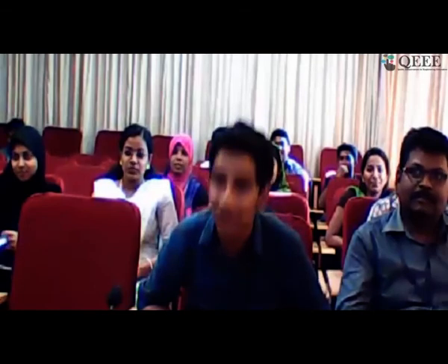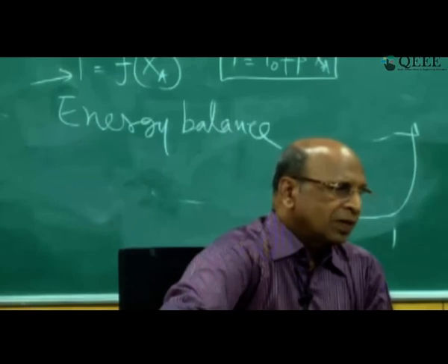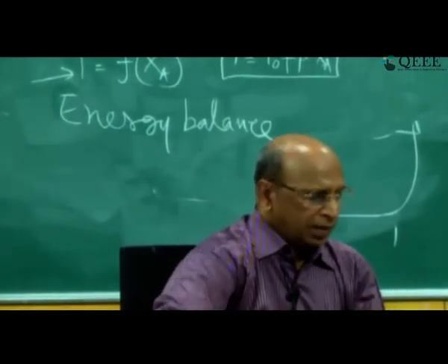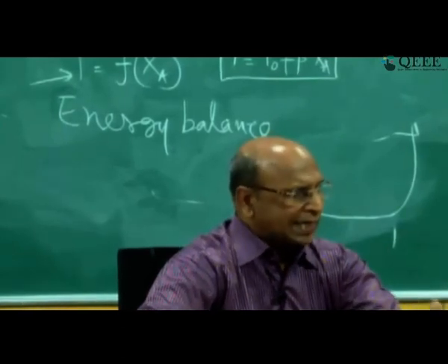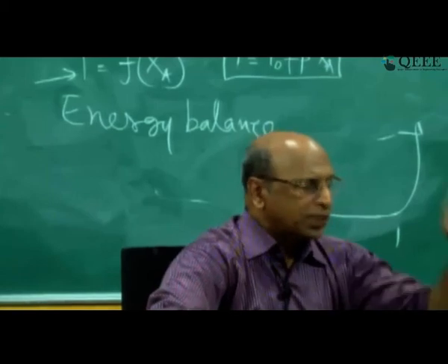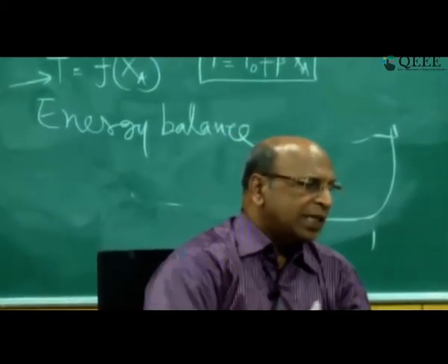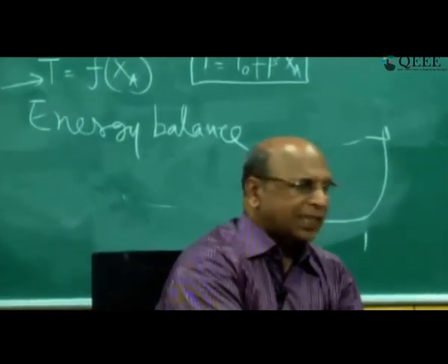In general, which reactor is more advantageous? I think I told you this. Always, for n greater than 0 reactions, plug flow is the best. Why? Because each and every particle is spending exactly the same time. You are supposed to get more conversion in that.